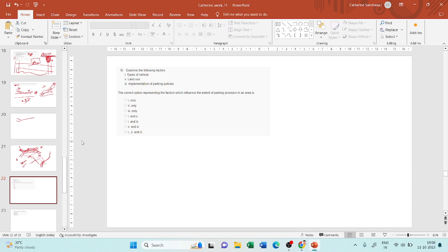Okay. So on-street parking, as the name says, on the road itself, by the side of the road, you will provide a space for parking, which you will call on-street parking. Off-street parking, as the name says again, is off the road limits, and we also have special parking. Okay. If you see IRC SP12, you can find the guidelines for parking facilities.